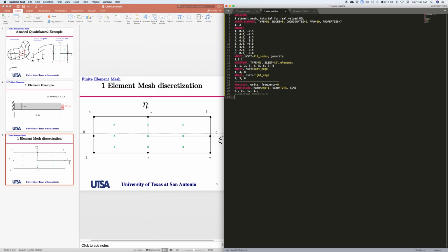Okay, so the way you do it is asterisk, which is calling an intrinsic Abaqus function, and it's going to be UEL property, and that property is going to be assigned to the element set. How do we call that one? All elements. So I'm just going to copy that name. That means that you can have multiple sections defined by elements, so you can assign different material properties. Okay.